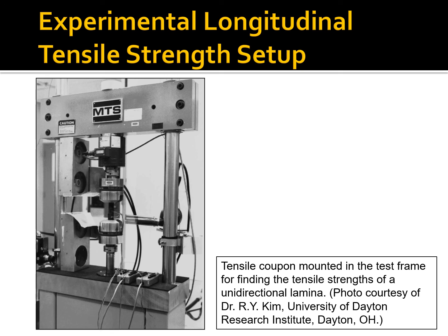The tensile loads are applied to the specimen at the rate of about maybe half to 1 millimeter per minute, and then you're taking about maybe 40-50 points for the stress and strain until the specimen fails. So let's look at a graph of a typical test.